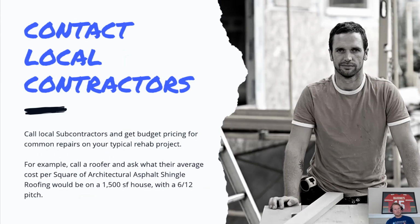So go head over to Lowe's and Home Depot, and then also contact local contractors for pricing. So Lowe's and Home Depot, that's where you'll learn about material prices. The other aspect of that is you need to learn about labor prices and installation prices. So in order to do that, you need to contact local contractors for pricing. So you can call a roofer and you can ask them, what would you typically charge for an asphalt shingle roof on an average 1,500 square foot house, and they might be able to give you a rough budget price. So they might say, oh, that's around $300 a square typically. So that would be a good rough budget for you that you could use in your preliminary estimates.